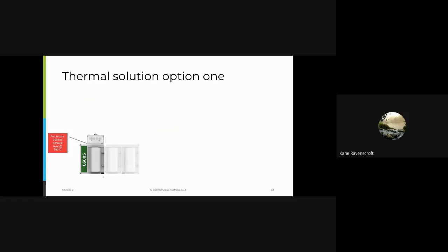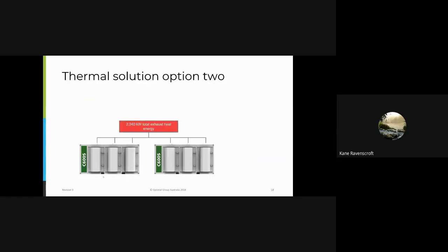And we've got a simple solution, basically an onboard hot water heater or heat recovery module that gives us about 250 kilowatts. So reasonably efficient, but we still lose 140 kilowatts. So we still lose about 35% of the heat, which we don't recover for a number of reasons. But the big challenge with this customer is that they're really a steam user. There's not a lot of use for hot water, and a lot of industrial customers tell us the same thing: not worried about hot water, we want steam.